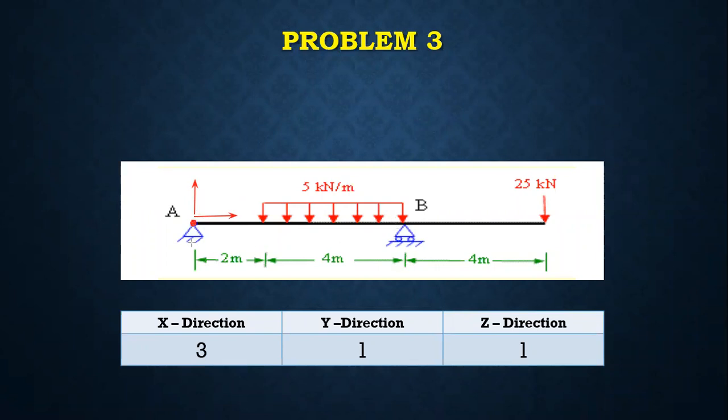As I told you, it depends upon the number of supports, but one more factor is the overhang. In order to tackle the problem clearly, you can choose the number of grid lines as 3. The other option is to choose 2 grid lines along the x direction and create one more node. The third grid is optional here. Again, the y direction is 1 and the z direction is 1.